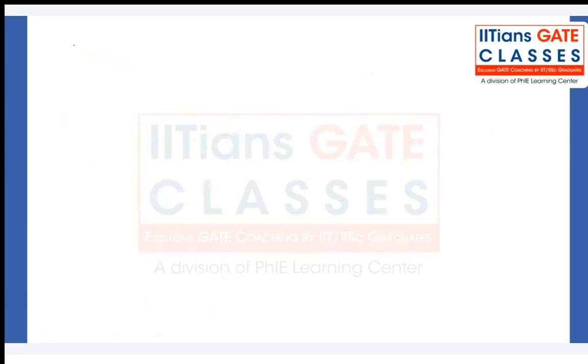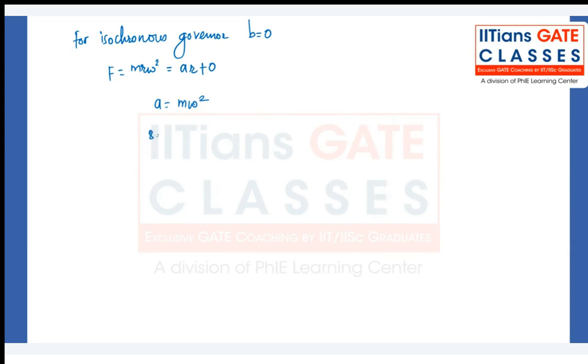We know for an isochronous governor, B is equal to 0. So F is equal to m r omega square, which is E times R plus 0, correct? Then you can say E has to be equal to m omega square in this case. So E is 8.75 Newton per millimeter.